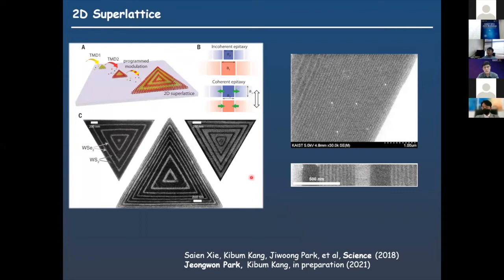With the advanced nucleation control, 2D TMDs can also form unique lateral heterostructures like these images. You know, the direction of thin film deposition is naturally vertical, deposit A and deposit B, which is pretty general. However, with the 2D layered structure, we can form lateral direction heterostructures. And now we are looking at a MoS2 and WSe2 monolayer heterostructure, where the width can be controlled within 10 nanometers, which is very amazing.